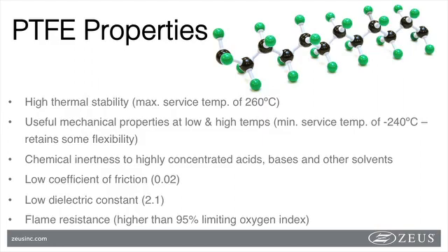Solvent molecules cannot penetrate the sheath, making PTFE extremely chemically inert. Alongside, PTFE has the electronic balance and neutrality to further repel any foreign substance with which it comes in contact. So, the characteristics of fluorine atoms and carbon-fluorine bonds allow PTFE to possess very attractive properties, such as high melting point, high thermal stability, low solubility, low friction, and extremely low surface energy.